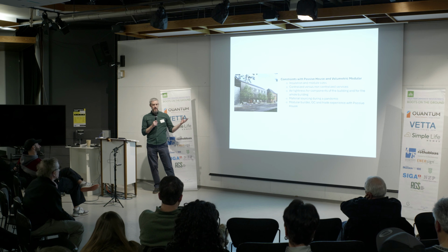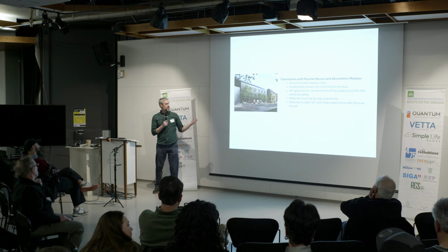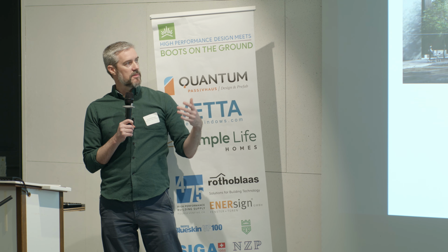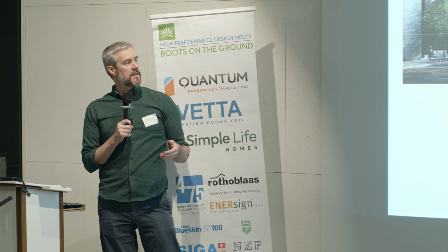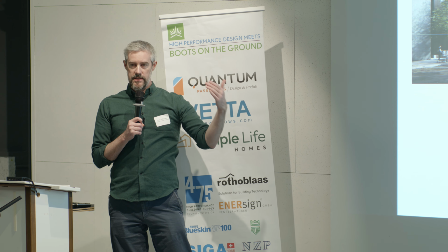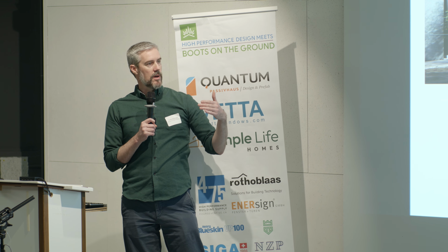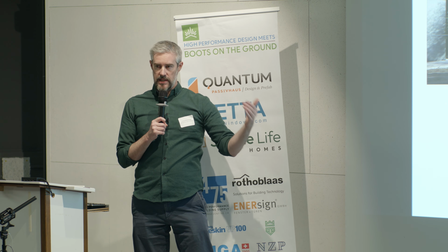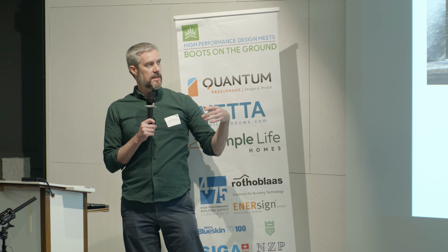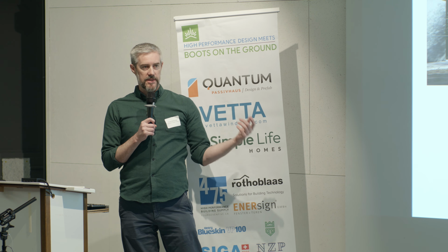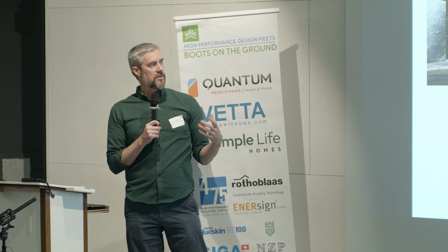For transportation of full volumetric modular projects, there's a lot of nuances in terms of permits that can drive the cost of the project. And so for us to put a lot of outboard insulation on the projects meant that we were going over a certain dimension size that necessitated police escort for the modules to be delivered to site and specific permits that drove up the cost.